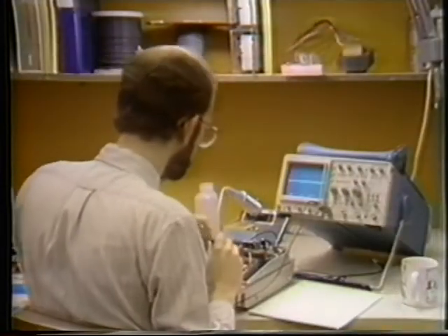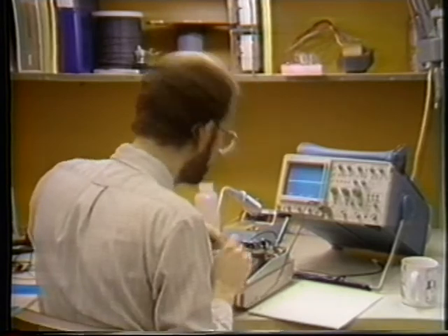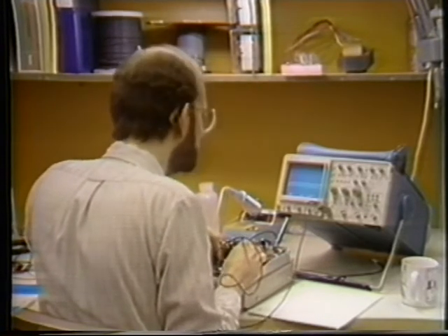If you think about it, probe bandwidth specifications don't mean much without aberration specifications. So, if you're going to view fast signals on a high-speed scope, use a high-speed probe. By matching those general probe and scope specifications, you'll create a system that does not degrade the performance of either component. Is that all there is to it? Well, no. As you'll see in later sections, specific kinds of probes may have additional specifications to consider.